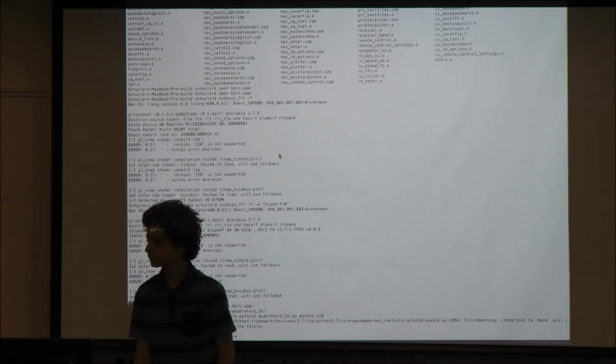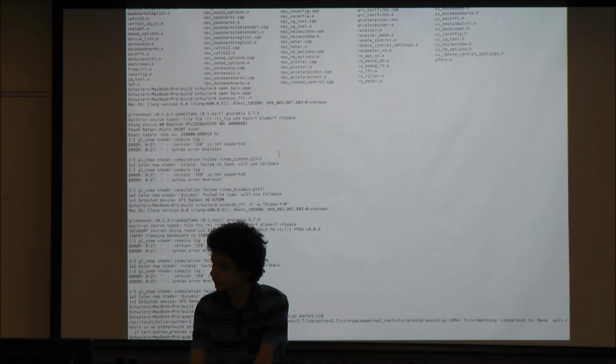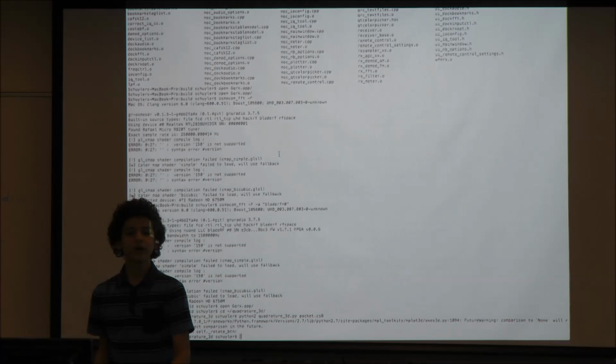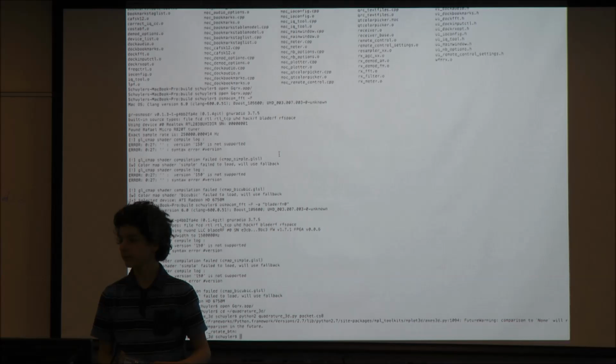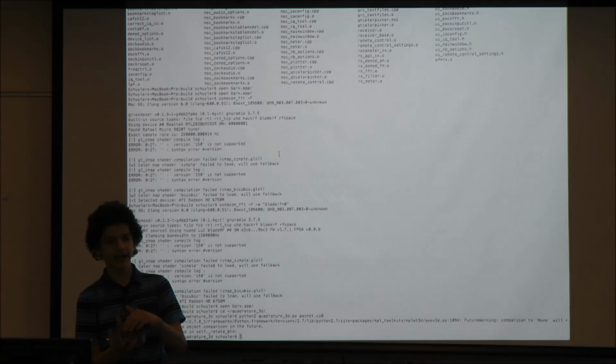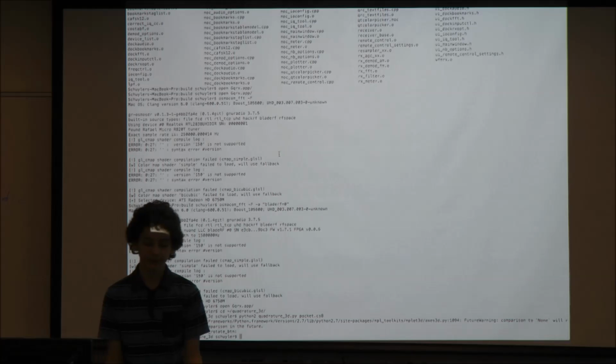Well, the technology that I saw uses an FPGA. If you want to do frequency hop, you want to use a DSP, something a whole lot faster, to calculate it. But yeah, the tuner still has to be able to tune to the frequency, unless you're within the band. Well, what you could do is interleave the tuners, so you put 2 tuners or 4 tuners, depending on how fast you want to switch. And then you have the tuners tuning, and you enable each to the antenna as you walk around. Or you have 2 antennas too. Another thing you could do is have the FPGA, where you program it, you give it a stream of frequencies to tune to in a time order, and it will do that for you. A lot of it's how good is your programming ability.